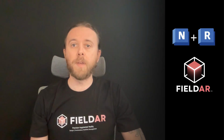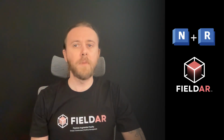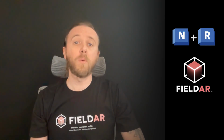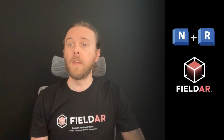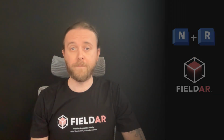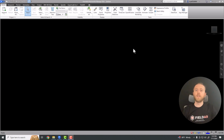So breaking up your BIM makes model loading at the job site much more efficient and also gives you more control over updating individual model chunks, which is very easy to do with the FieldAR plugins. We will review this workflow more in depth, so let's get started by installing the FieldAR plugins for Navisworks and Revit. To continue with this tutorial, you'll need Navisworks Manage or Revit, or both, installed in your Windows machine.